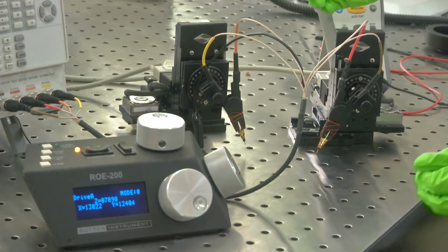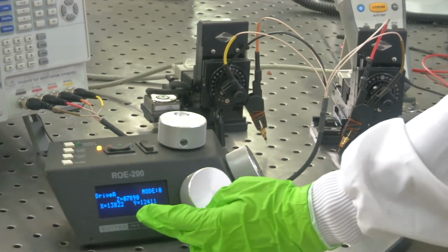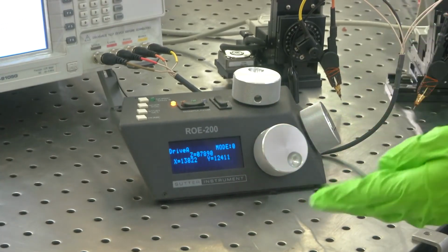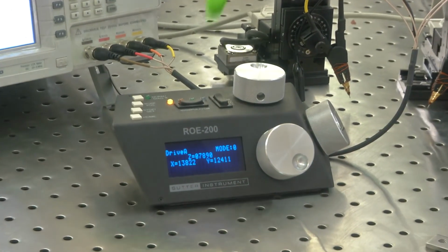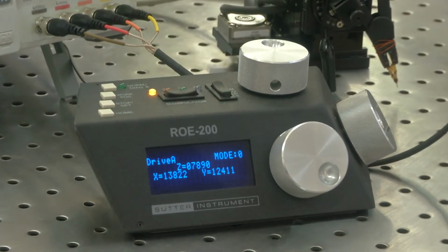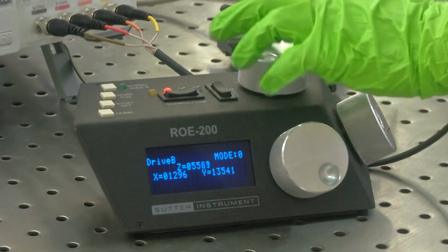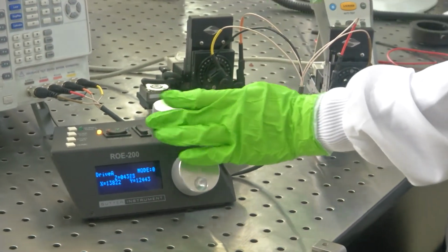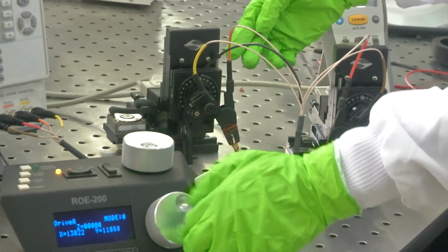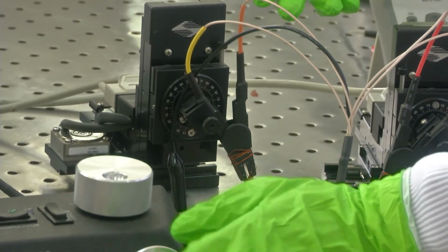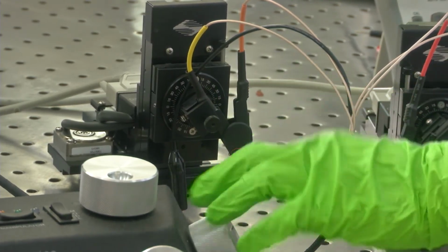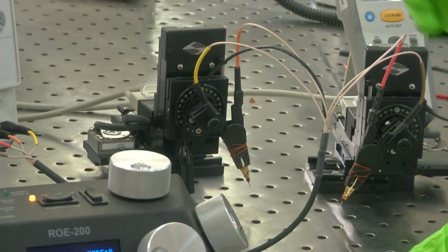Okay. You can see here the absolute values of the coordinates of each micromanipulator end effector. I can change between the two. There are two of them. We can individually control every one of them. You can see this one moving up and down, or you can see that this one moves up, and we can also translate them in Y direction as well as X direction. This is how you use a micromanipulator for this measurement.